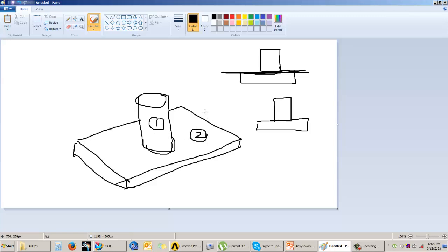Now when these are two separate bodies, this is one sweepable geometry in this direction where there is no discontinuity, it is one uniform structure in this direction. Similarly, this base plate is also sweepable in this direction, that means it is one single plate. So with this, now I can generate hexahedral elements.